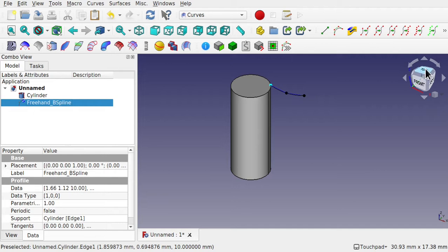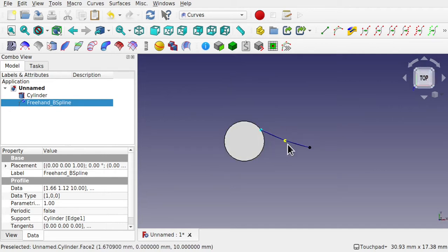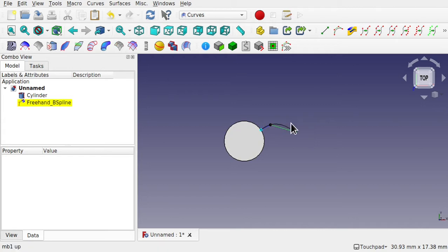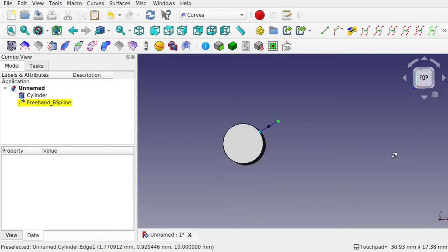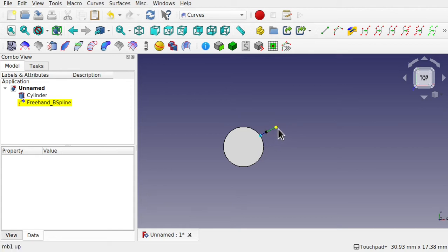Now the best idea is to come to the top, because the projection of this will change the X, Y and Z location of these points. So if I'm working from the top, then I'm only projecting in one direction, and I know this can be flat. So I know that hasn't changed anything along the Z axis, because the Z is pointing straight up. It's still the same as where it was before because we clicked on top. We're only modifying the X and Y. So I'm going to bring these in, and I want a small lip on here.